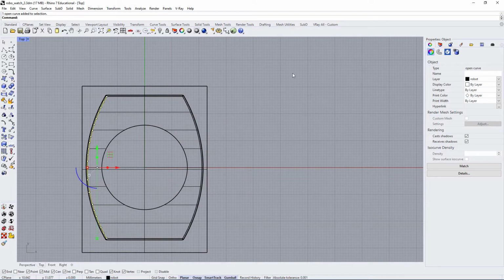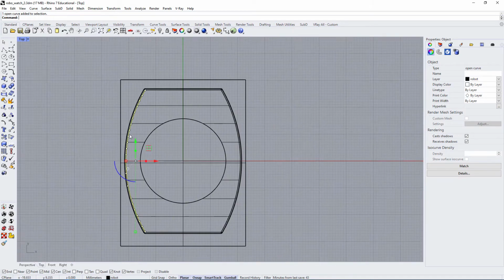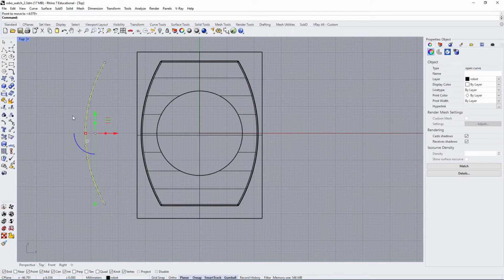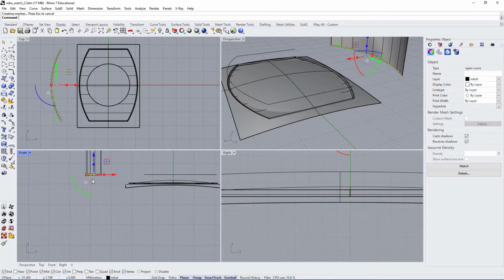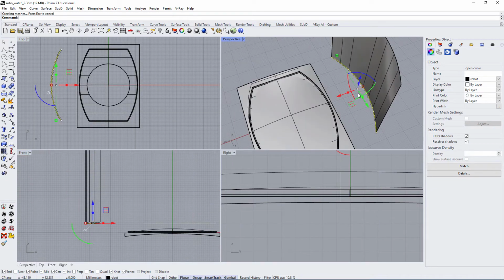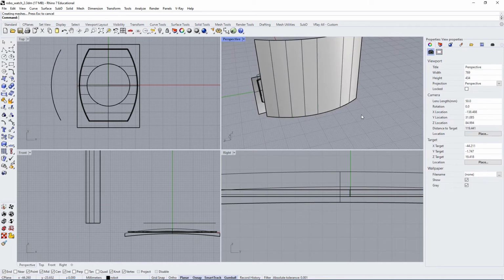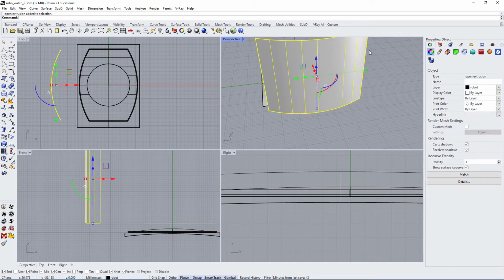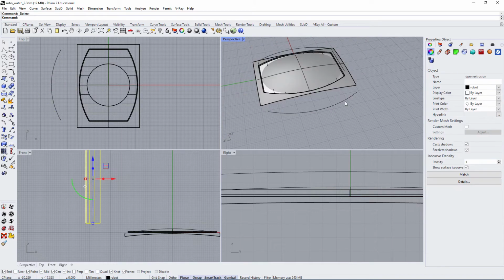And then once you have that, if you want it to be a single curve as opposed to something like this, where if I extrude it, you'll see it still remains a bunch of small patches. No, it did not. So sometimes when you extrude it, it breaks it up into patches, and sometimes it does not. Typically the reason why it does that is because of the relationships.